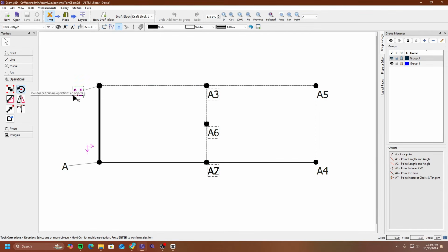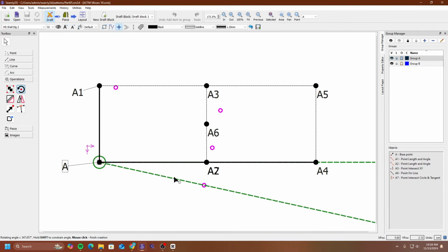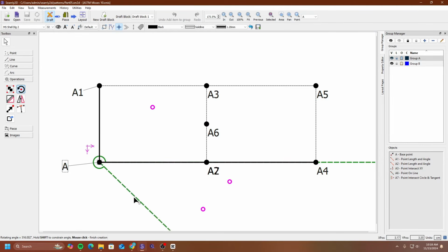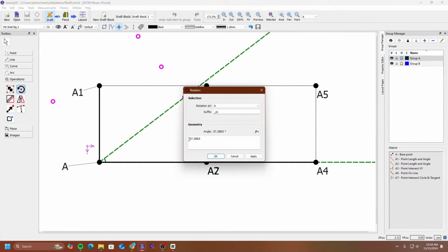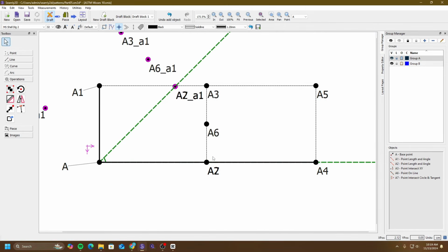this left half. And once you've selected what you want to include, if I want to add more, I can hit Control to make sure I'm including point A and click that. And then we'll press enter to confirm my selection. And now I need to choose what point I want to rotate it about. So if I want to rotate this portion about point A, I click point A as my center of rotation, and then I click to determine the angle, let's say 45 degrees, where I would want that to go.